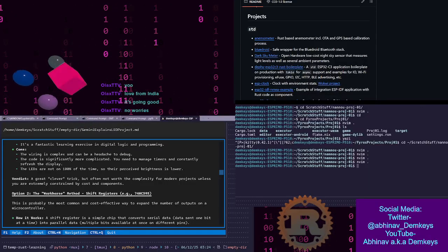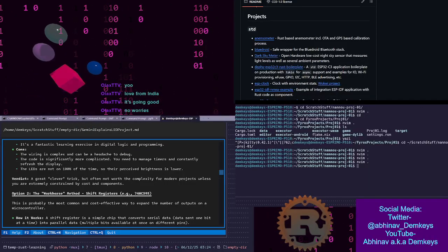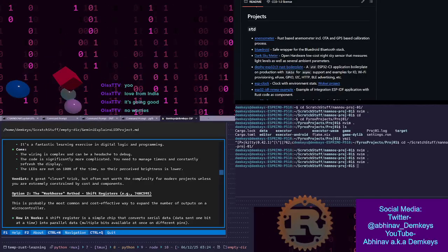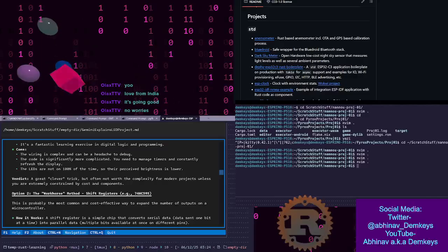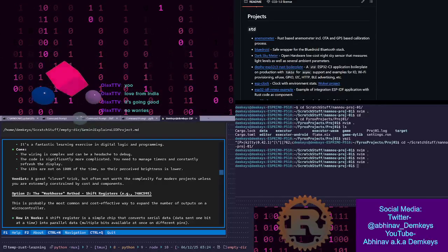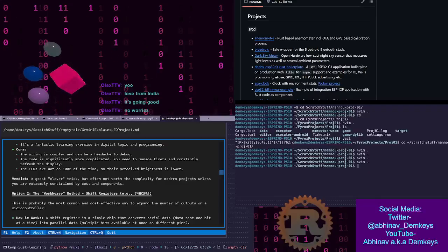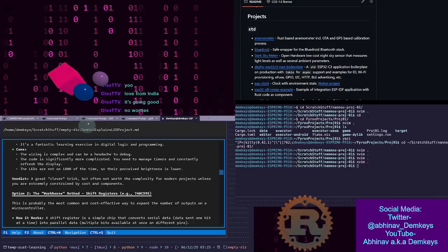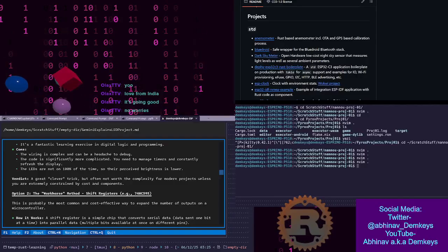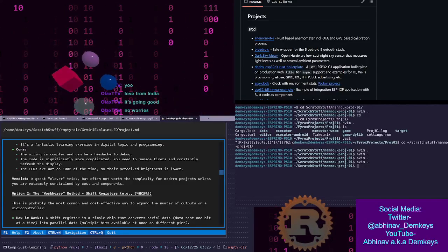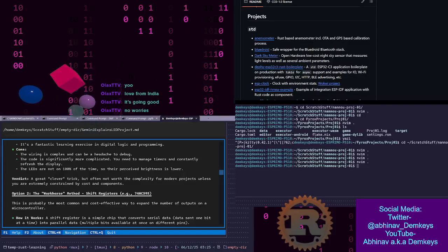In my case, I built it so I could hack a bunch of electronics that I have. And this was the simplest way without having to actually join both the circuits together, because when you join both the circuits together, then you have to join their grounds together, and then you have to worry about one side of the circuit accidentally powering the other side, or any sort of short circuit somewhere.